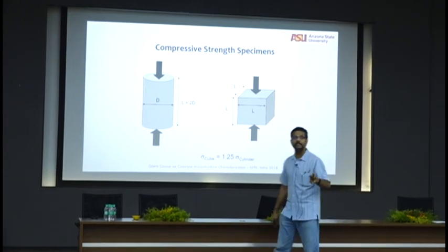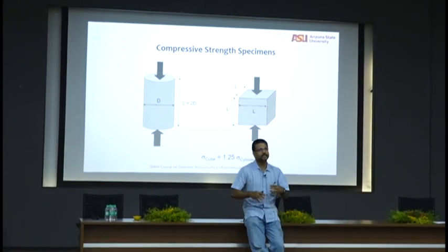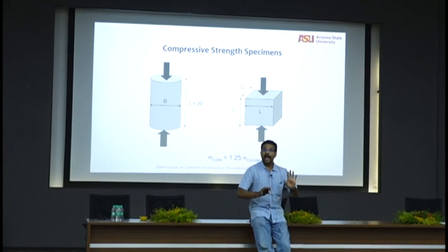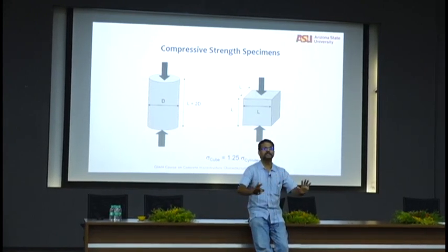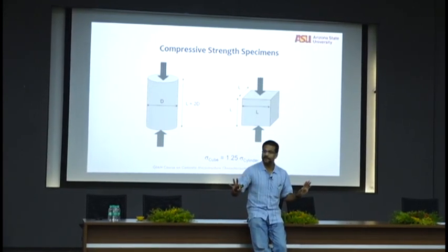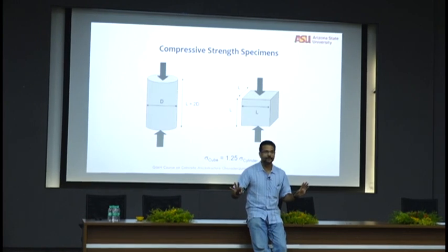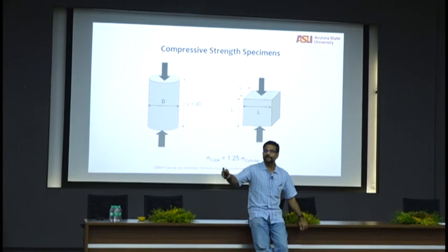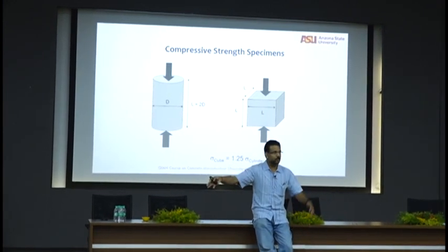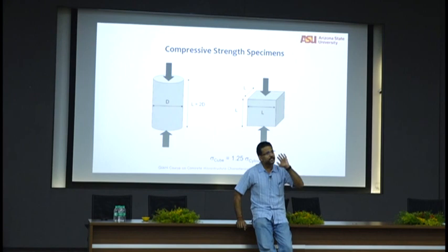They keep changing the design specifications, they keep changing different things. And the most changes happen with respect to shear design of concrete structures, especially when you start reclassifying different zones as earthquake prone zones. So a zone in 2000 might not have been an earthquake prone zone, might be zone 3, now it might go into zone 4, so you have to redesign it. So shear design changes a lot. Flexural design has not changed, doesn't have to change.